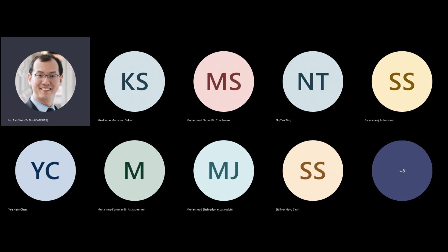So you have them complementary. The fast switching will be enabled by this one, and it will compensate for the slow switching of the PMOS when it's a logic 1. When there's a logic 0 here, the PMOS will be the one that's switching quickly, and the NMOS will be the one switching slowly. So that's the reason for actually having the complementary structure here.